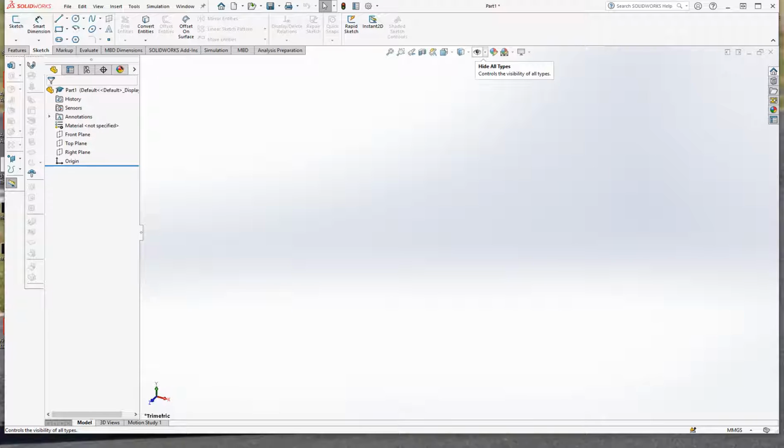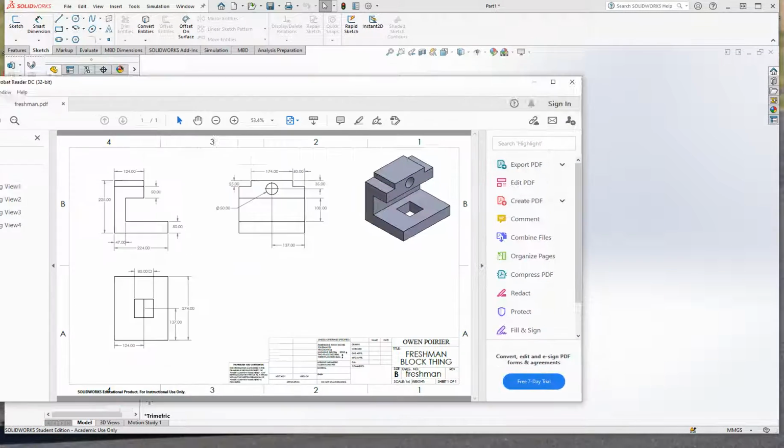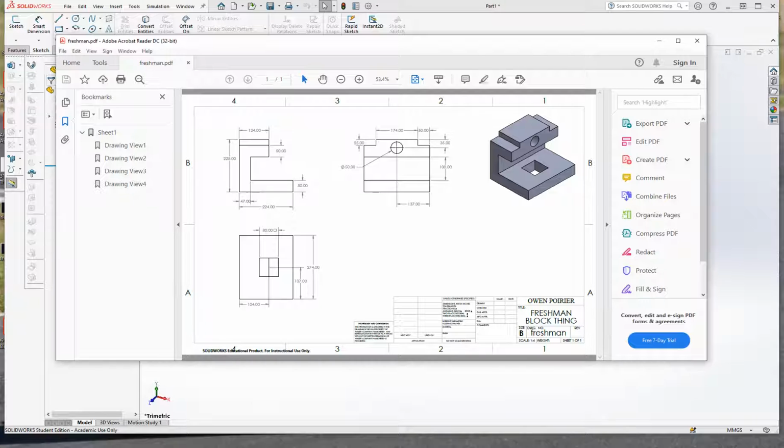And then you have the eyeball icon here in the center. The first thing I'm going to do is just look at the drop down. So the eyeball is turned on, and one thing you want to make sure you have turned on is the origin. Okay, this little blue L shows up, and then you just click somewhere in the screen. And I'm going to drag in the part just quickly. This is the part that you guys are going to be drawing.